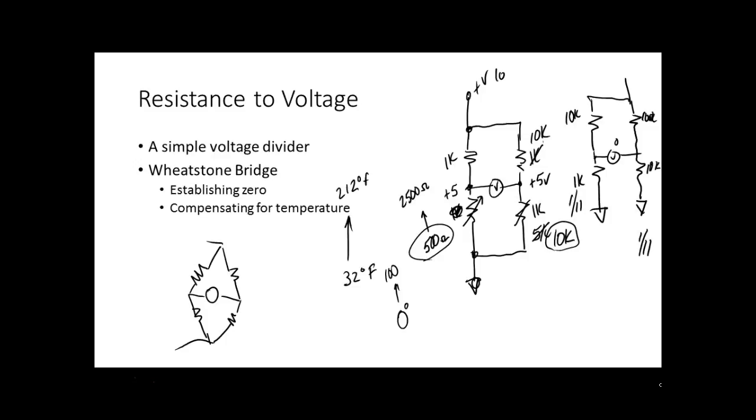So it's real easy to see what we can do with the Wheatstone Bridge: not only can we set a zero reference, but we can also tell if it goes above that reference or if it goes what? Below. Okay, so when you say that reference, what are you doing with the sensor itself? I mean, you put it in whatever you reference it to. If it's a pressure sensor, I might put it under 100 psi. Okay, I see. Or I might put it in a vacuum. 0 psi is really hard. Or put it in a vacuum, right? You understand? If we could put it in a vacuum, then that would give me a 0 psi reference. So something that you know.